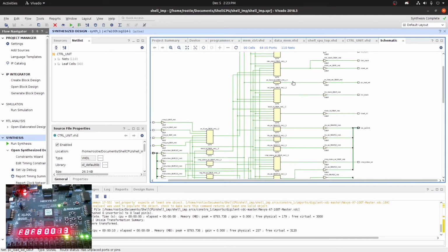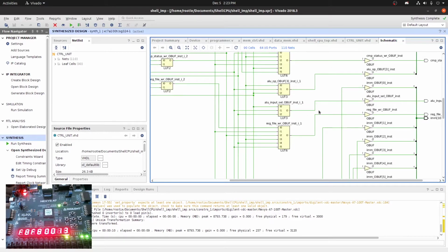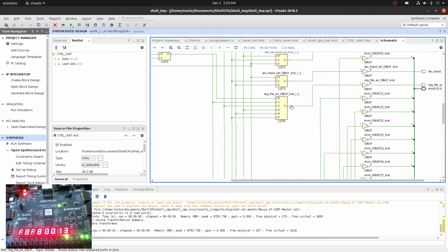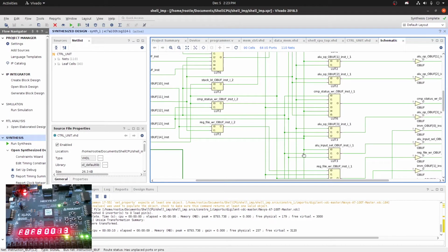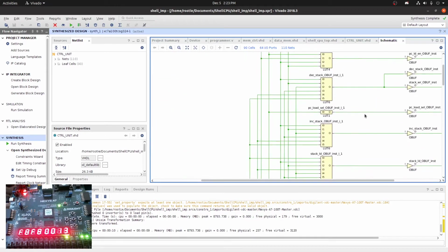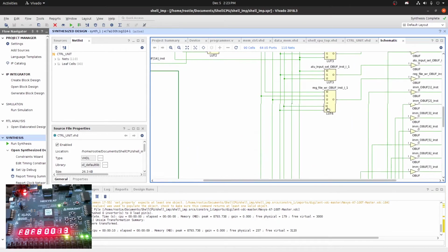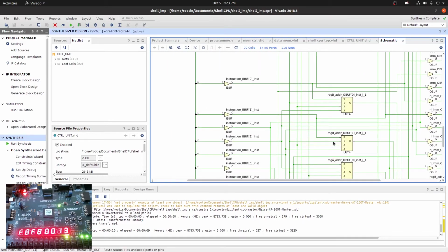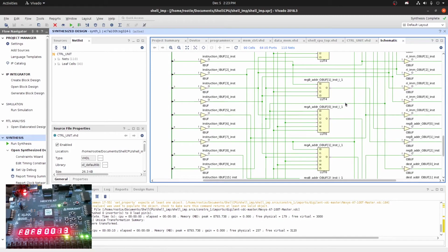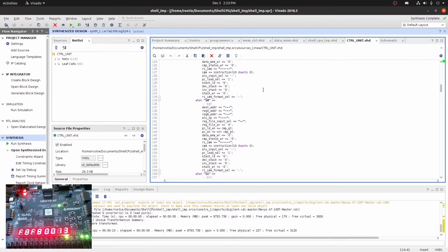It'll be really obvious if you messed up, because there'll be certain elements in this design that are not combinational logic. They're not lookup tables. They're latches or FDREs or some sort of flip-flop. That's going to be a big red flag because it's not part of a combinational circuit, and there's no clock involved, and you don't have one of those. So it's important.